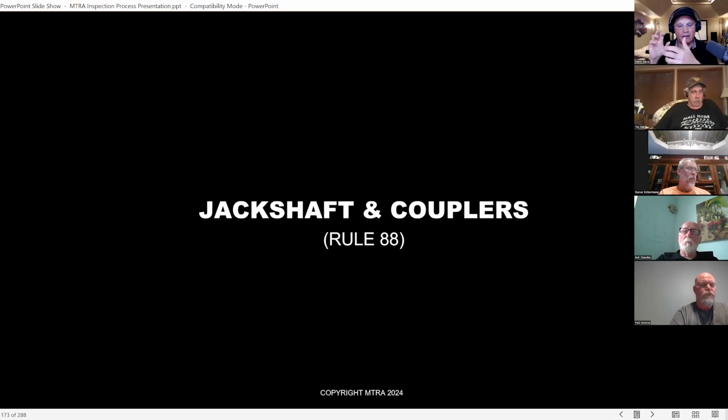If not, every time you're moving around, even just driving around the pits, any time the axle's rocking, it's working on those welds if you don't have a rotator. Back in the day when we had flat stock for loops, they were elastic enough that they could flex, but these are so rigid, so overbuilt, that they don't allow for that. They'll break, or something's going to break if you try to articulate them and they're solid mounted.